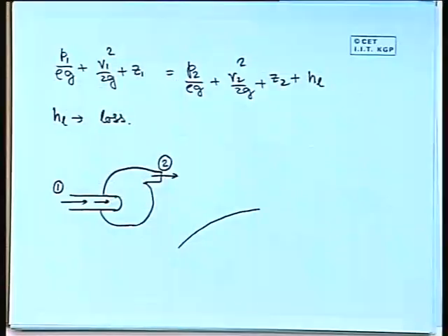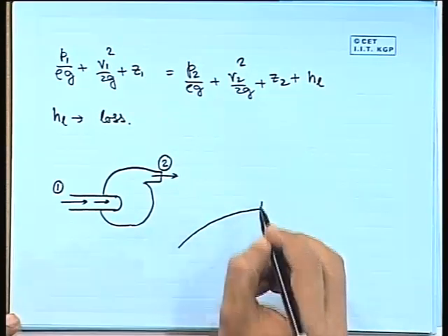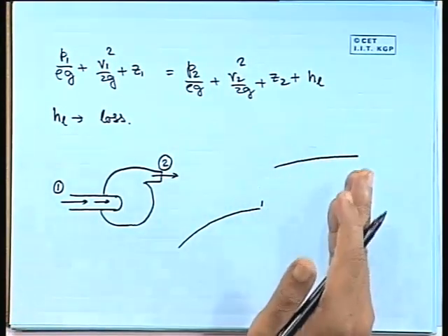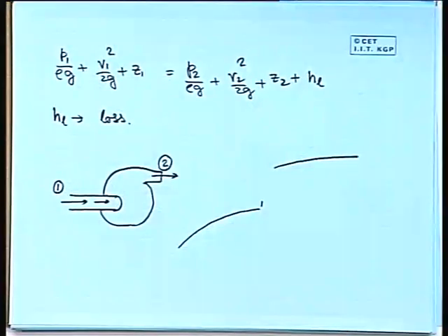If there is energy input, let us say there was a streamline, along this streamline we had some sort of energy which is constant mechanical energy. As soon as this energy input is there, streamlines we will get with some other energy constant. So, obviously, we cannot write the summation of flow energy, kinetic energy and potential energy here is equal to the summation of flow energy, kinetic energy and potential energy at the outlet of the machine.